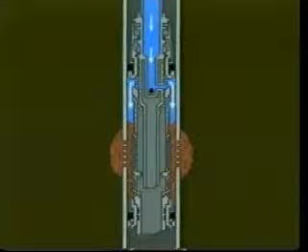While in this position, returns are shut off and squeeze pressure is applied to further consolidate the gravel pack. Application of upstrain releases the indicating ring, permitting further upward movement of the setting tool crossover assembly into the reversing position. In this position, the wash pipe is above the O-ring seal sub. The lower seals of the setting tool crossover assembly are above the seal bore sub, and the seals above the gravel pack port are still in the packer bore.